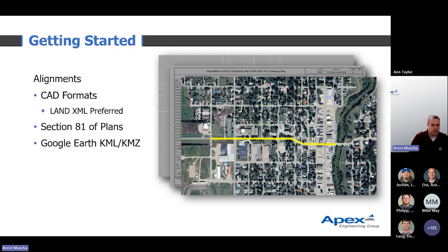Only thing with that, if you draw it in Google Earth, you're going to want to make sure your left and right offsets are probably not going to be as accurate as if you have an alignment that you build.